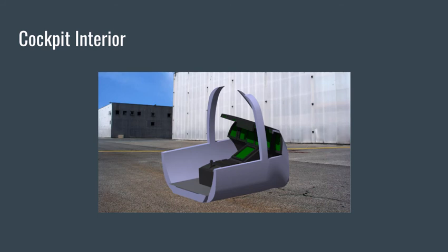The control panel was made using the same procedure with the addition of padding some sketches and pocketing holes in the surfaces. A multiple extract was done on the contour of the whole cockpit to be able to split the excess. This made the control panel take the form of the cockpit structure. The joystick was made by combining sketches and then using the combine tool.